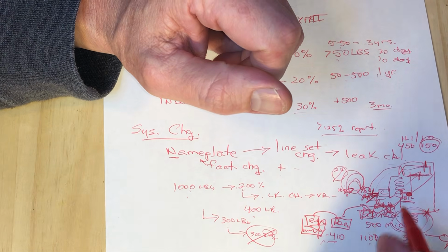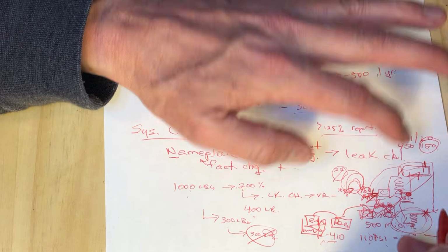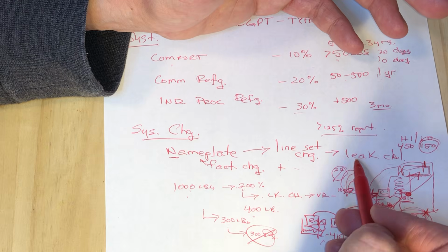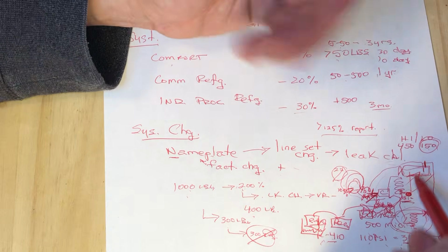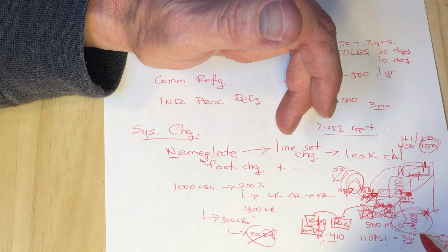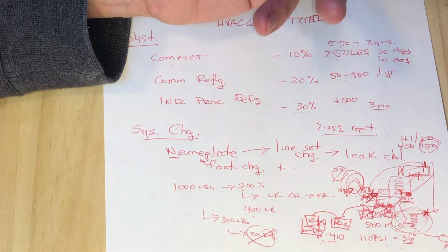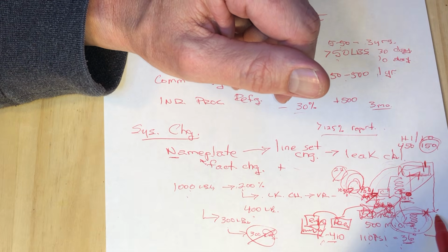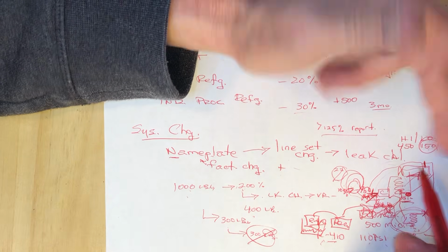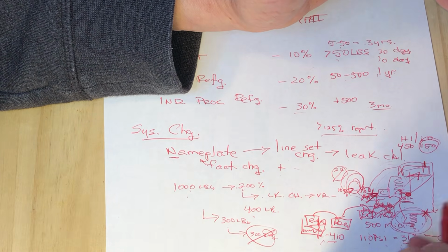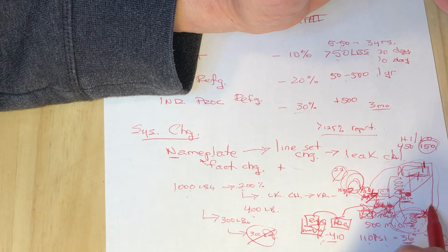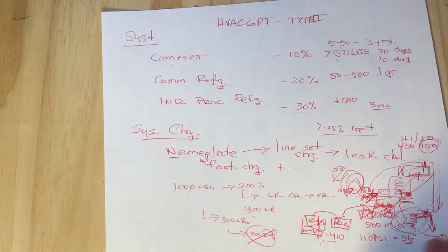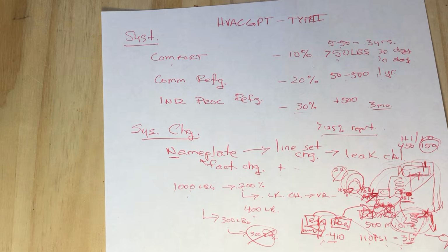The other technique that you could do is if this has a long refrigerant line set run, because it was maybe going from the first floor here, this condensing unit that you maybe pumped everything in the receiver, now has an air conditioning evaporator on the 9th floor, up 9 stories. Or maybe the other way around, the condenser's up on the roof and the evaporators are down 9 stories. You're going to want to get it from the liquid line entering the evaporator right there, because all the refrigerant is going to be gravity moving, wanting to flow downward, and it's easier to go from the recovery machine into the tank. So there's a couple techniques that you can enhance your skills with on that.